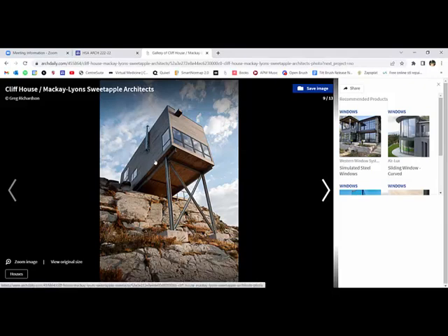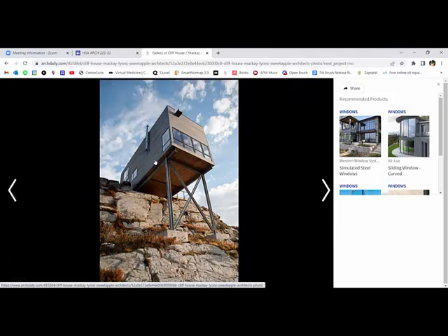Is there any way to get the tool to go in all three directions? So the question is, can I get the sweep tool to go in all three directions, so in X, Y, and Z? And the answer is yes, but not through generic models. That's where we get into defining a three-dimensional curve with the custom mass tools. And we will get there, but not as part of this precedent. We'll do some advanced modeling technique stuff, but definitely not as part of this project.